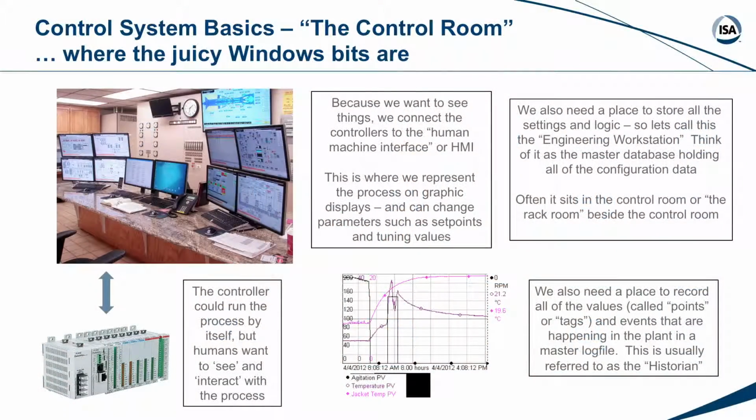You'd go through the stack, literally the stack of printouts that printer generated overnight with a highlighter and say, okay, FI 6748 was in alarm 600 times last night. We should go look at the settings on that one, right? Thankfully now we've got some mechanisms to port that into databases and into spreadsheets, and we can prioritize those alarms, right? And get a better handle on it.